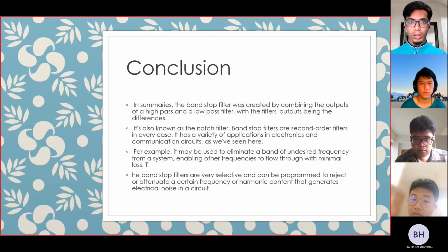So for the conclusion, to summarize, the bandstop filter is created by combining the output of a high pass and a low pass filter, with the filter output being the difference. It is also known as the notch filter.